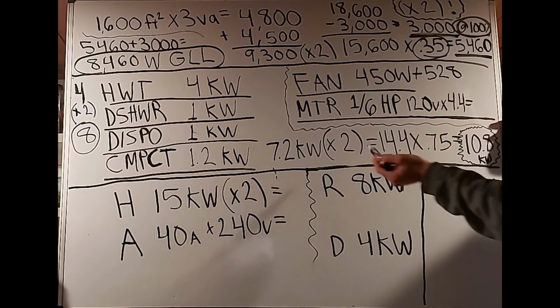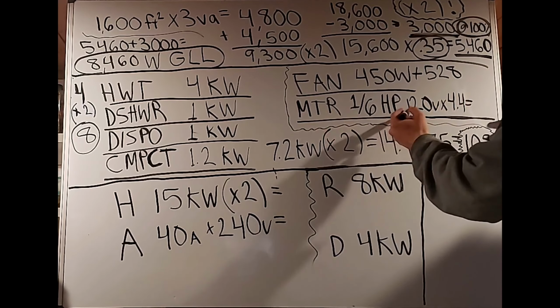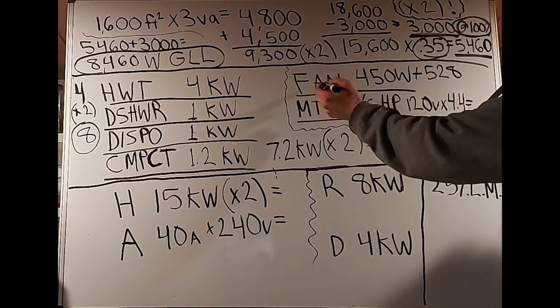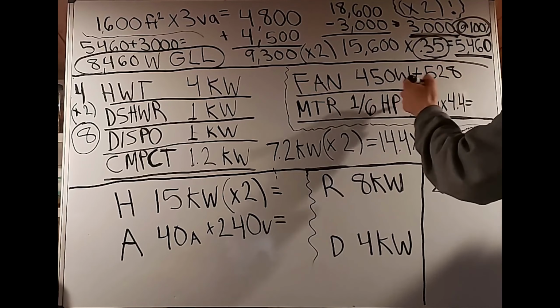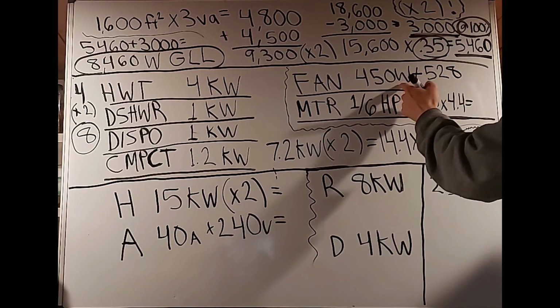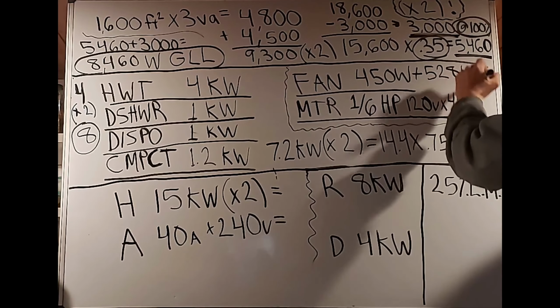Okay, since we now have our load for the motor, we're going to add the fan and the motor load together. Of course, we see 450 watts plus 528 watts.